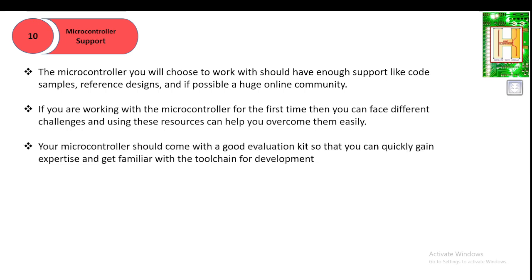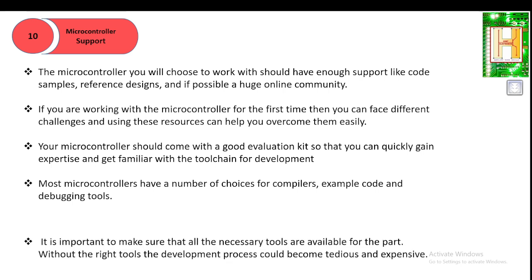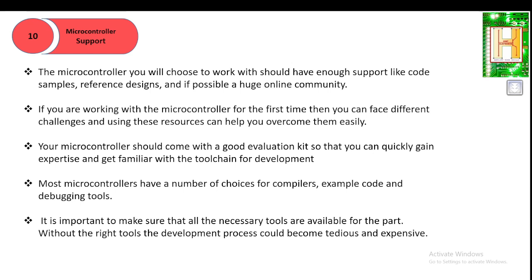Your microcontroller should have a good emulation kit. For each microcontroller which you are going to select, there should be a good development kit where you can very easily practice and get familiar with the tool chain and the development process of the microcontroller, and later on you can design your own PCB depending upon it. Most microcontrollers have a number of choices of compilers, example codes, and debugging tools. It is most important to make sure that all the necessary tools are available for the part. Without the right tools, the development process could be difficult and expensive in the future.